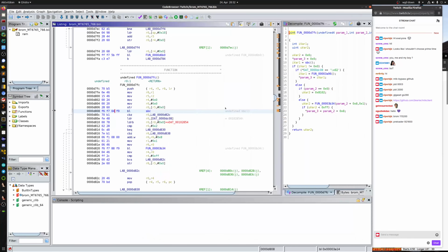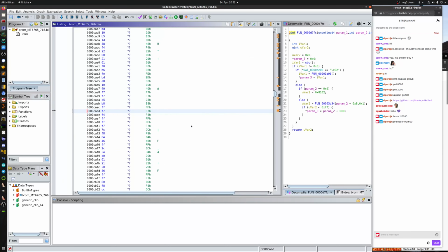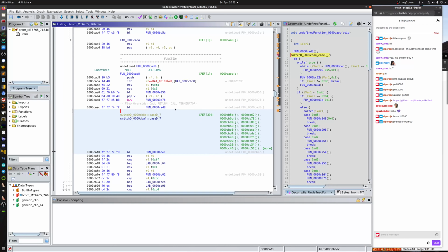It's better. So on boot you've got the preloader init, and in the preloader init, it's going to initialize UART, and in the UART initialization, it's going to start the command handler. Yeah, it hasn't been disassembled, so we're going to do that now.